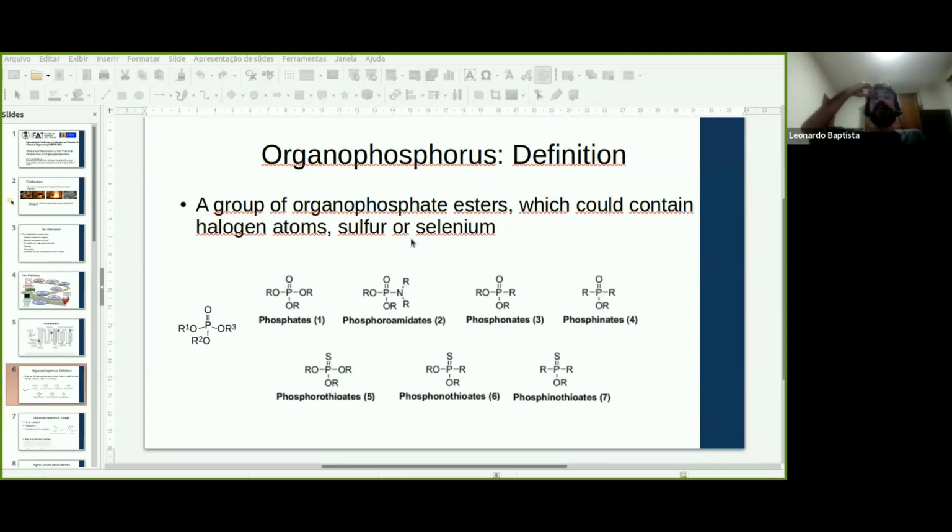In the continuous flow reactor, the temperature and the mass flow of the organophosphorus need to be carefully chosen, because some organophosphorus compounds are flame retardants, and depending on the temperature and the mass flow, they can quench the incinerator, lowering the temperature and extinguishing the flame in the incinerator.